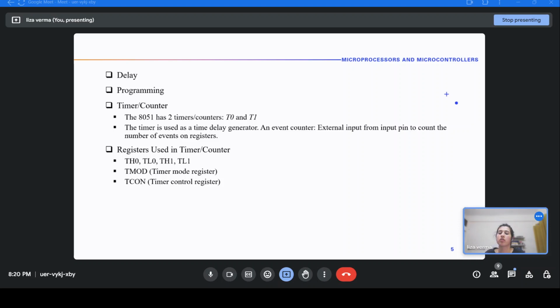TH0, TL0. They are 4-bit, right? Each. No, I mean there are no 4-bit wide registers. No, no, total 8-bit actually. 8-bit for TH0, 8-bit for TL0. So the total timer T0 is 16-bit. It's not one register, but the two registers make up for the one timer.